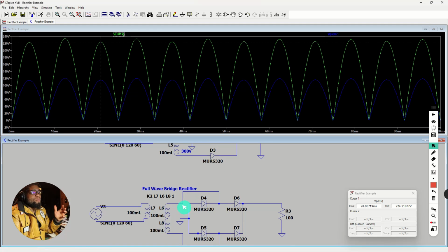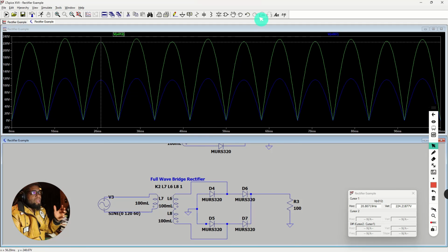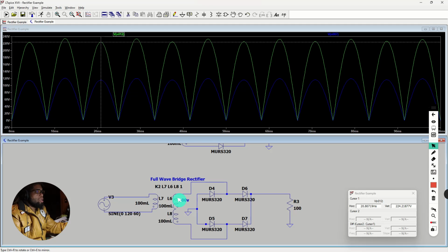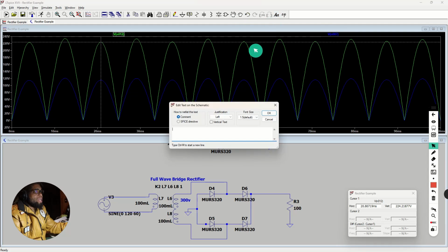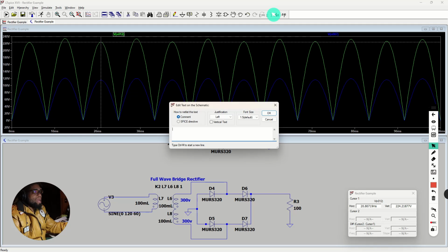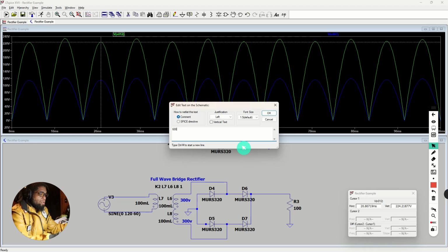With the full wave bridge rectifier, if I took that same transformer and had 300 volts on one side, 300 volts on the next side, and I wasn't using the center tap, so there was no 0, I'll just leave the 0 out, the center tap is not there. That is going to effectively give me 600 volts off the output, okay?